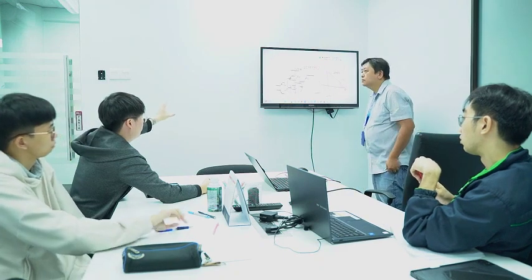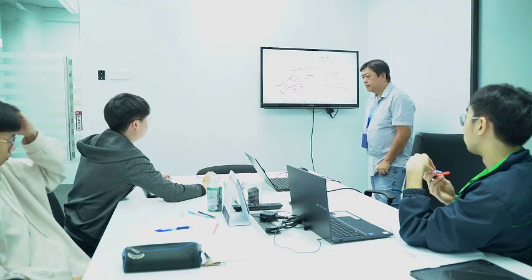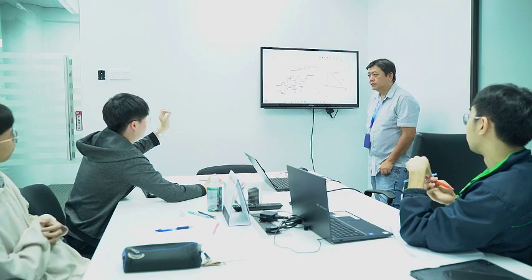What I'm trying to say is, when you have 1 over S, that means you have a pole right at the origin. So at that point, the signal will immediately drop by 20 dB per decade. But then there's also another one, which is 1 plus SRC. That means there's also another pole, a normal pole, somewhere on the right side. Once you reach that point, the signal will drop by another minus 20, so in total it becomes minus 40.